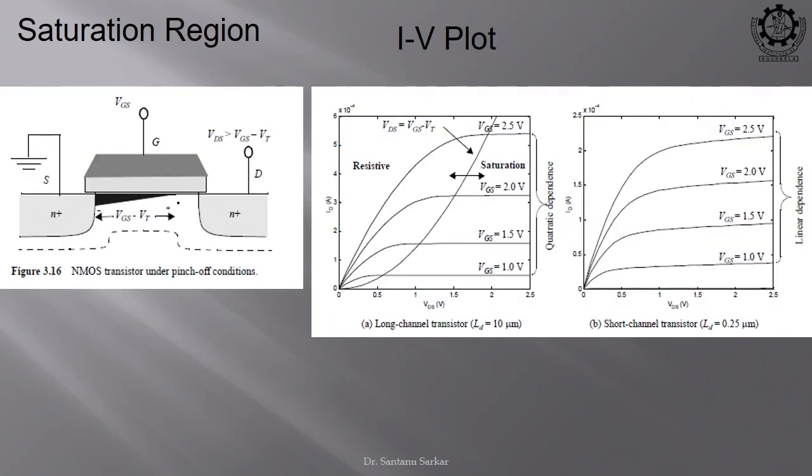So, that is the tapering that we are talking about. If we have a drain voltage that is higher than your overdrive voltage, then what will happen? Suppose this VDS is just equal to VGS minus VT. Then the effective field will start after VGS minus VT, and at this moment it will just equate each other. The effective field that is forming the inversion of the channel is VGS minus VTH, and this voltage is also VGS minus VTH. So, it will just end at this moment.